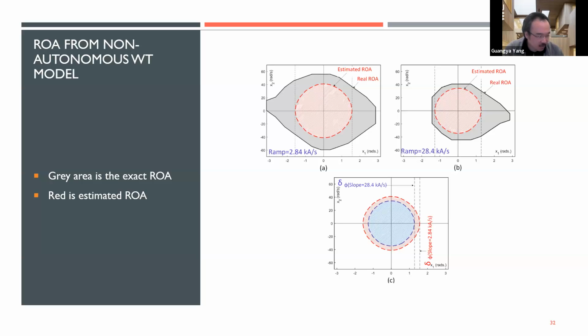And that is also something that the grid code maybe didn't consider from a nonlinear stability point of view. They would like to have the active power go back to normal as soon as possible, because during fault ride through, if you have a lot of converters in the system, the active current is low and the reactive current is high, and after the fault, to keep the system frequency stable, you would like to have a higher active current back to normal. But this high active current could also drive the system to an unstable region.